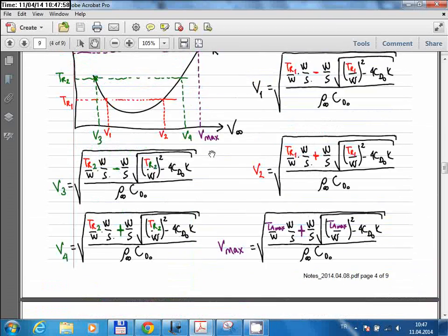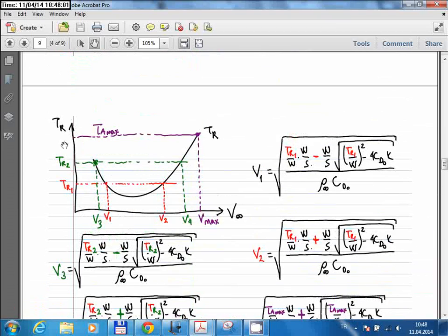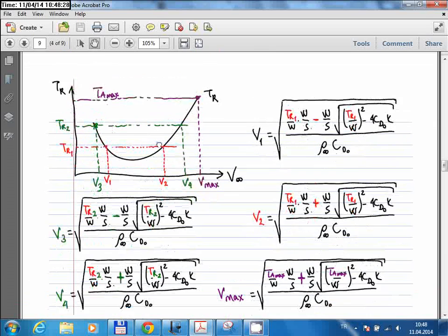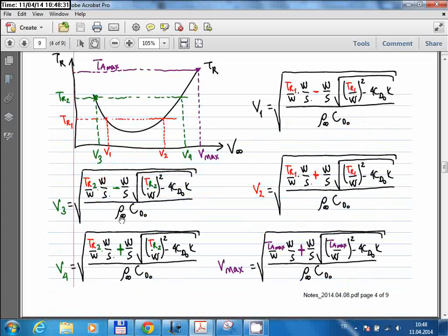And then if you know your drag force, there are two possibilities for an equilibrium flight, for a steady level flight, and you see these possibilities on this graph here. So you can either be flying at this point of the drag curve or this point of the drag curve, and you can find the intersecting points either graphically. From the graph we can read what the corresponding speed values are, or you can use the equation and find the exact speed values.